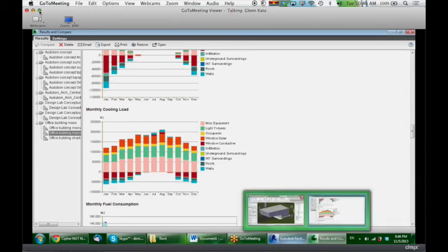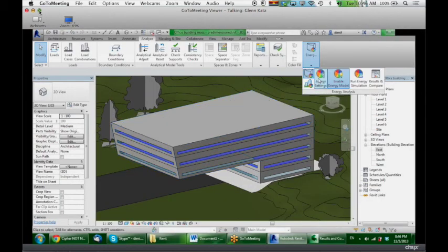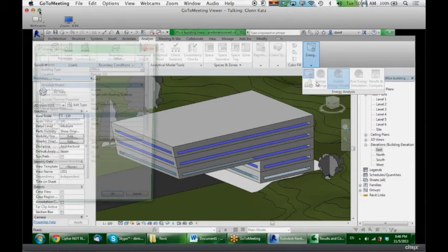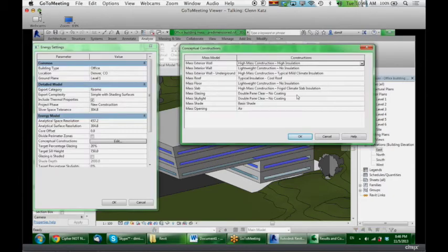When we actually get into doing the real building modeling, then we can be very precise about the material, the thicknesses, and really drive a U value that you want the window to have. So at this quick, get your answer in 10 minutes level, you get 4 or 5 different choices, but not as much variability. But if you take it one step further, we can go to the web and get some more control or really do the true modeling of the finished materials.